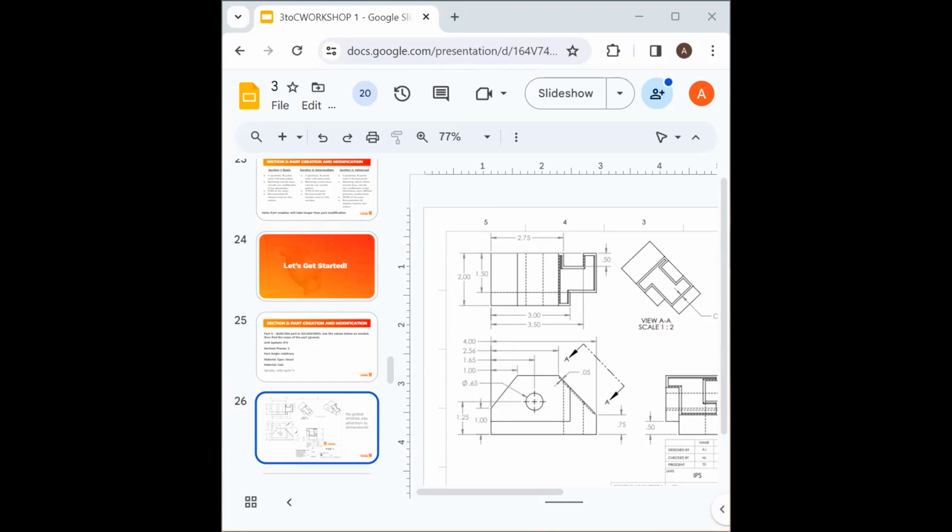That one's fully defined. So you'll notice here that these blue lines aren't defined, and it means that I'm missing the relation. And since it's moving, it tells me that I need to move this real quick. Make this coincident to this line, or make it collinear. And now it's fully defined. So because these are now fully defined, I can do my extrude cut.